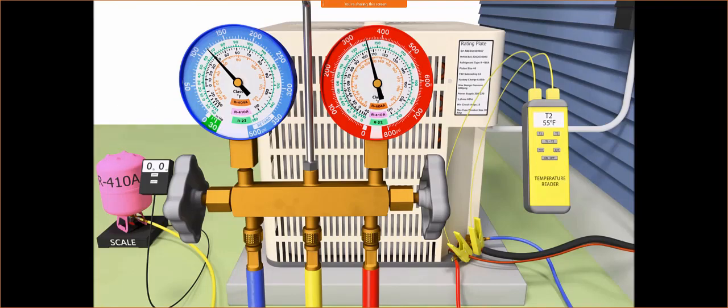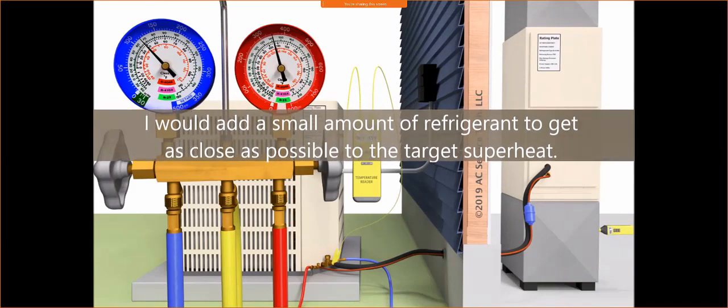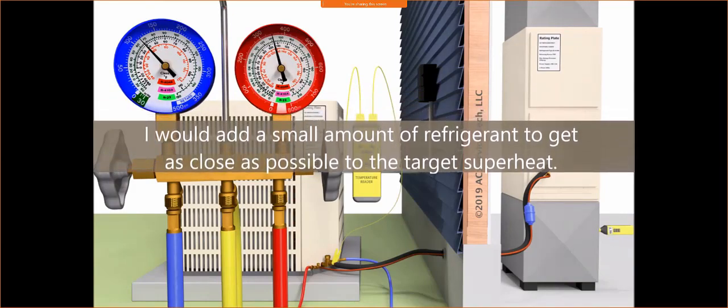You really want to find that leak. You want to start looking for the leak with anti-corrosive bubble leak detector and maybe either an ultrasonic leak detector or a heated diode leak detector or something like that. But if you're just a little low on refrigerant, that may have escaped out of the Schrader valve, or maybe that was just from the service company checking the refrigerant charge each year. Every time you check the refrigerant charge, you are accidentally pulling a little bit of refrigerant out of the system. So that's a possibility as well. But this system would still work properly, only being 3 degrees off from what the target superheat would be.